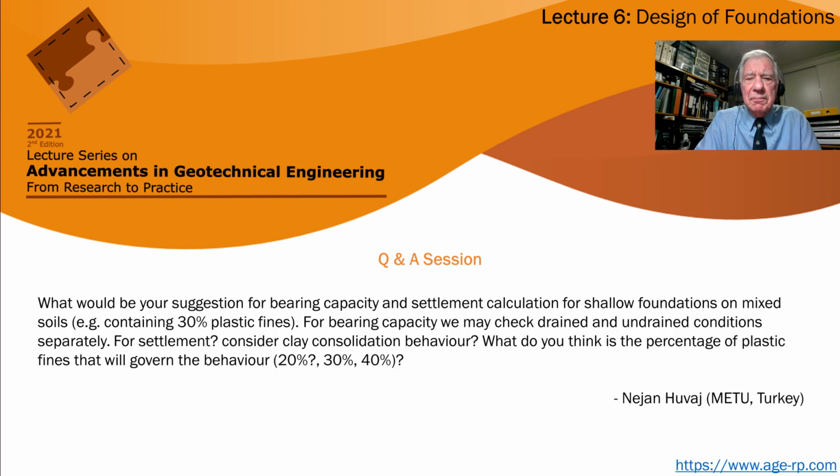What would your suggestion be for bearing capacity and settlement calculation for shallow foundations on mixed soils, for example, containing a mixture of fine and coarse-grained soils? For bearing capacity, we may check drained and undrained conditions separately. How about settlement? For example, consider clay consolidation behavior. What do you think the percentage of plastic fines that will govern the behavior? Is it 20, 30, or 40%?